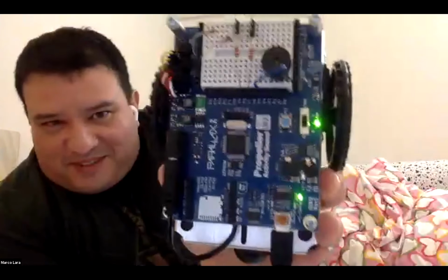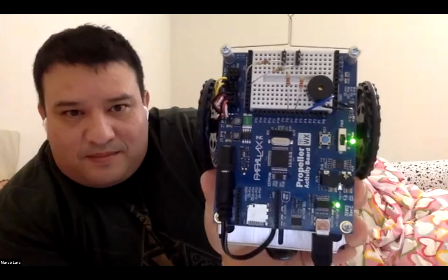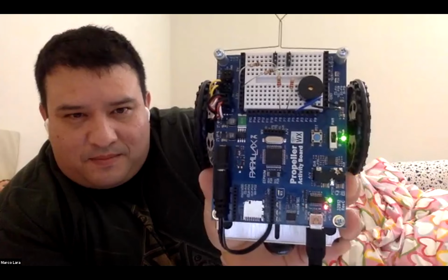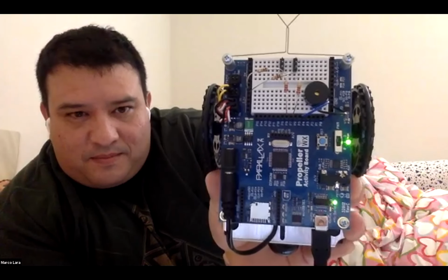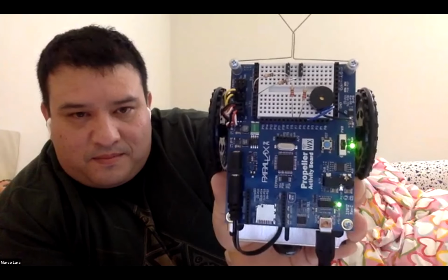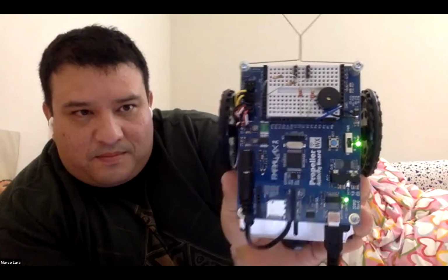Okay. Show us that again. Yeah, let's come back. I just took it off. Oh, no, that's good. So are those 10Ks yellow violet, the vertical resistors connected to 5 volts? They look like yellow violet, they don't look like brown, black, orange. Can you double check those to see if there should be red, red, brown going to the pins, but then brown, black, orange going to either 3 or 5V, I forget which.